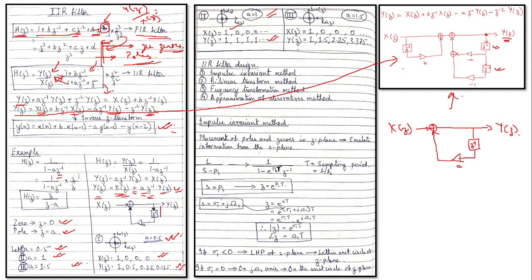In the third case, for the same impulse input, the values are continuously growing. So as time tends to infinity, there would be an unprecedented increase in the amplitude values. Okay. So from these three cases, what we see is, when the pole was within the unit circle, the h[n] values were coming down.